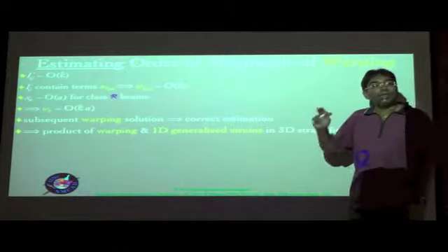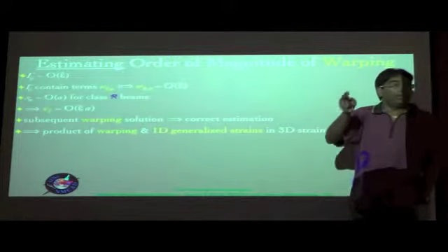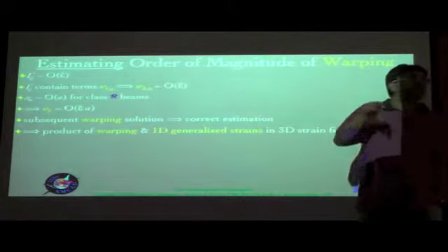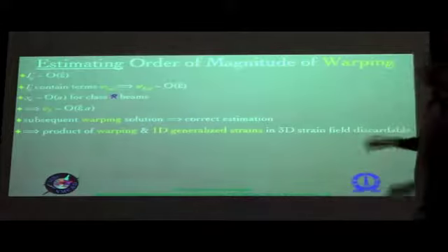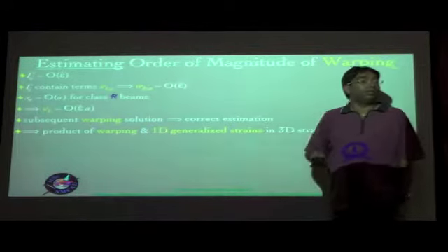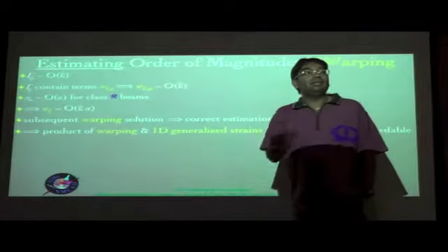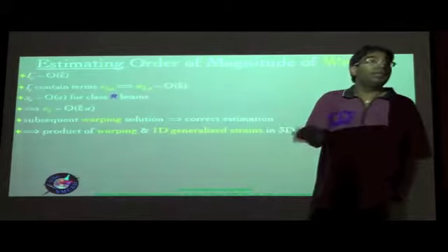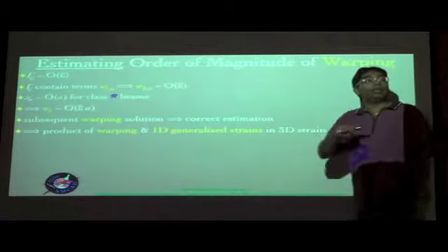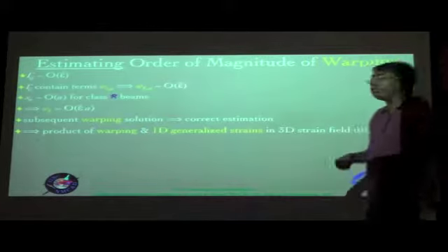So in many cases it is more convenient, in such examples where all the stiffness matrix terms are of the same order of magnitude, to drop off the higher order terms in the strain itself, rather than multiplying with the stiffness matrix, making it quadratic in the strains, expanding it out and then looking for the higher order terms to drop out.